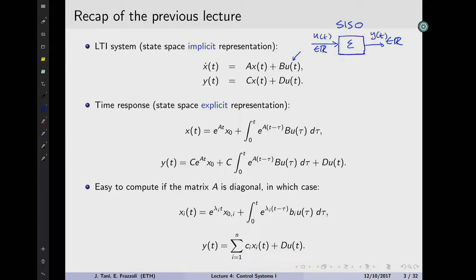It's described by this equation here, and we can represent it through a set of state variables x. Because although u and y are single numbers, even in a SISO system, x belongs to R^n. Okay, x is a vector of n variables, where n is called the order of the system. So if n is the order of the system, then we know y is a 1 by 1, so C must be a 1 by n, D will be a 1 by 1, A will be an n by n, and B will be an n by 1. Okay?